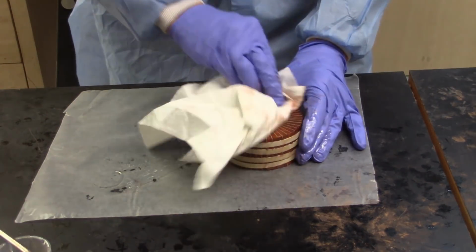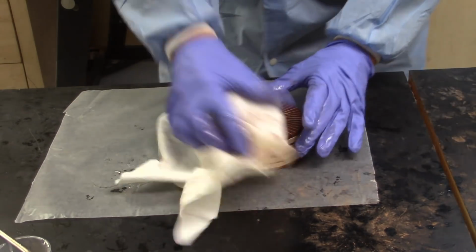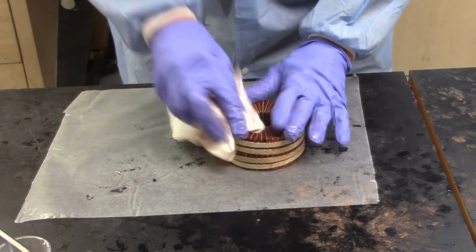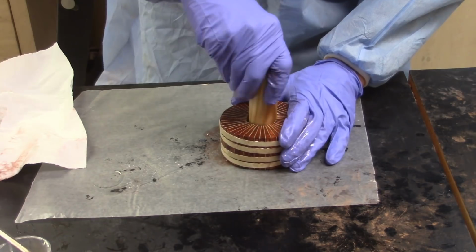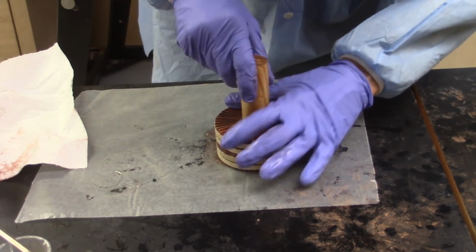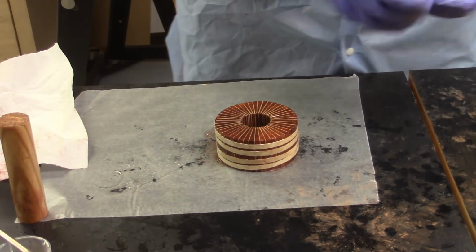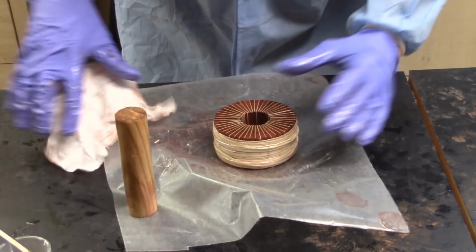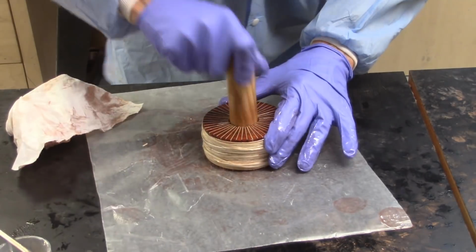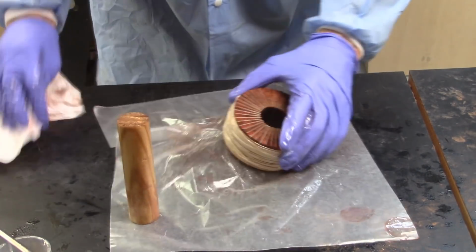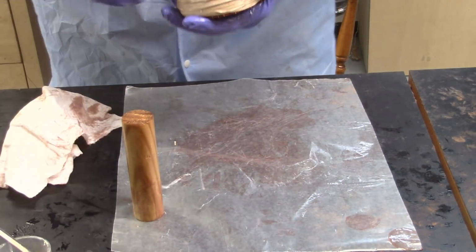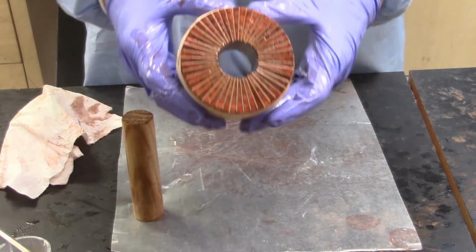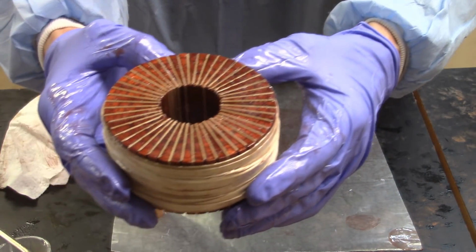I wipe off the excess epoxy glue that has seeped out of the joints. Finally, I use a dowel to clean up the inside of the assembly and to make sure that all of the maple spacers are properly aligned and none of the spacers overhang inside of the disc assembly. I use as many rubber bands as necessary to thoroughly clamp the assembly and provide for tight joints between all of the wood pieces. I allow the epoxy glued assemblies to dry and harden overnight.